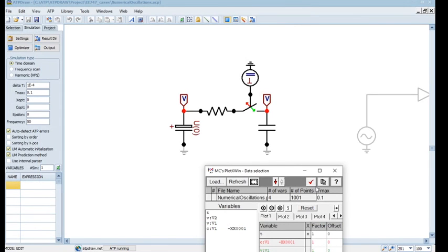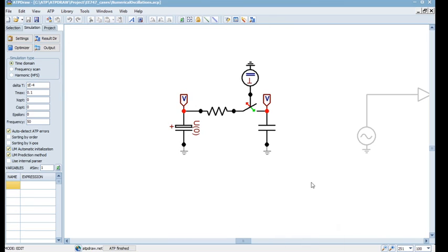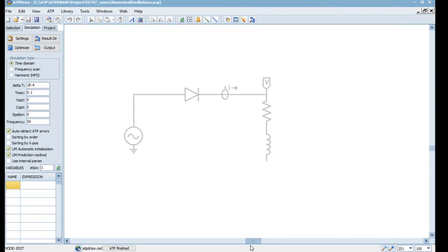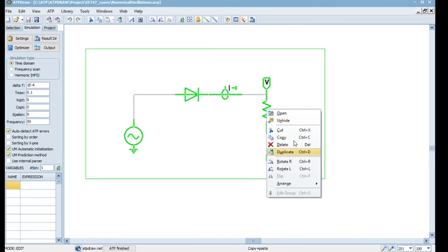So this is what numerical oscillations are, and they generally happen when you have a voltage interruption, like for a capacitor when you have a sudden change in voltage, and for an inductor when you have some kind of current interruption, like a quick current change, maybe when you open circuit it. Let me just show you.